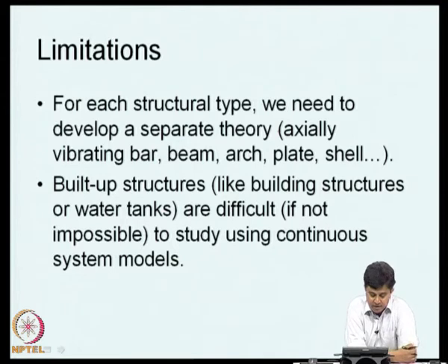The limitation of using continuous system models is that for each structural type we have to develop a model. I have been talking about the Euler-Bernoulli beam. So, you have to study an axial vibration problem, a beam problem where Euler-Bernoulli beam we discussed, and if you include shear deformation and rotary inertia, you have to develop a theory for the Timoshenko beam, and if you want to study an arch, you have to combine the theory of Euler-Bernoulli beam with axial vibration models, or if you are interested in deep arches, again you have to develop another theory. In 2 dimensions you have to deal with plane stress models, plane strain models, plates, shells and so on and so forth. So, each one you have to develop separately.